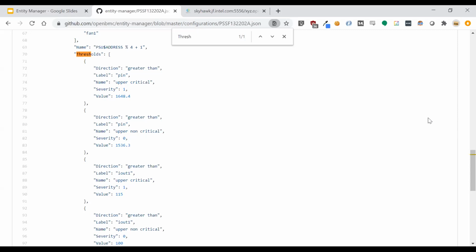We might have left it in there in case people want to use it, but for the most part, we've been using libgpiod and defining all the GPIOs in the device tree, and then using the GPIO name and libgpiod to get the GPIO. It's because the sysfs way is the bad way to do it, and everyone's moving to the character device, so we went that direction.